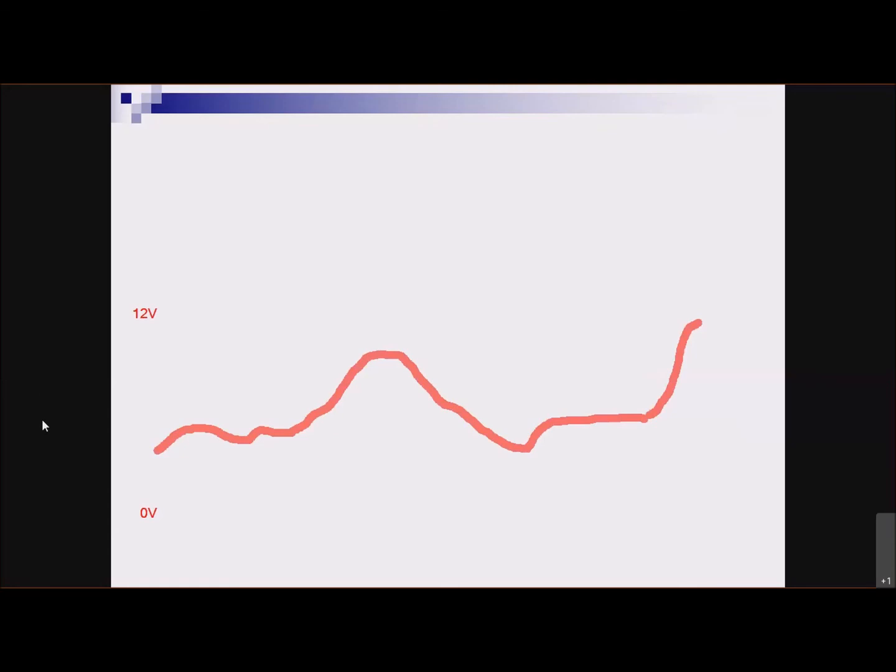So you can just use a regular DC voltmeter and watch this. You could write yourself a chart for different engine RPMs and loads and figure out, based on the voltage, how many grams per second are flowing through this thing. Typically, when you look at this on a scan tool, it may not even give you voltage. It may just give you grams per second and not even tell you what the actual voltage is. But you can stick a voltmeter on the signal wire from this thing. You can see what the actual voltage is, right?